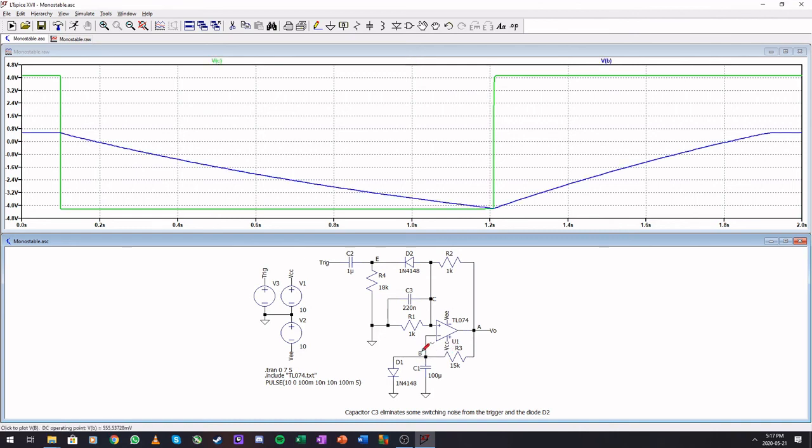Okay, the charging of this capacitor, see it's a diode voltage, and when it charges towards the limit, when it reaches the triggering point, it switches on. This is at 4.25, and then it gradually returns to this 0.7 volts. This time here is called the recovery time, and it's best not to have any input pulses before this has settled again, or else this time here becomes a bit unpredictable.